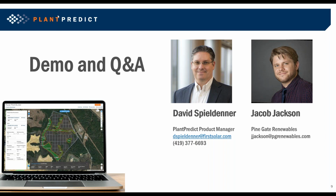And that power plant object, that power plant kind of like data object variable that's there, you can go and create a custom one in Python, but you might as well just use the ones that Stephen Kaplan, again, another shout out to Stephen Kaplan, created, and use the objects that are in the SDK, because what that object has, you define that variable as power plant or whatever you want to name it, and then it has all the parameters that you would ever need within that object, and you can change the tilt angle, you can change the loss factors, you can change everything about it locally, and that's instantaneous.